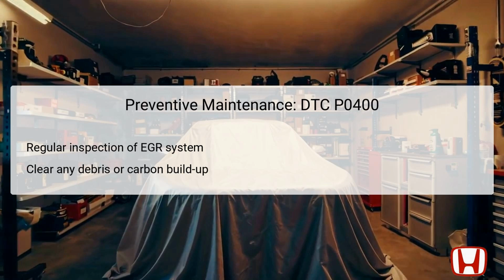Cleaning the EGR valve to remove any debris or carbon buildup can significantly prolong its lifespan and functionality. This maintenance helps ensure that the EGR valve operates correctly and minimizes the likelihood of facing emissions-related trouble codes. Additionally, keeping the exhaust system clean and free from obstructions promotes better engine performance and efficiency, contributing to the vehicle's overall health.